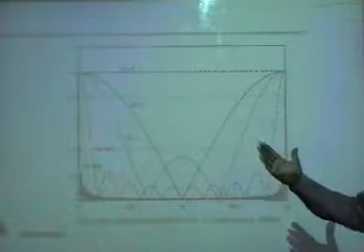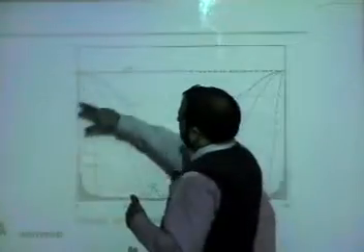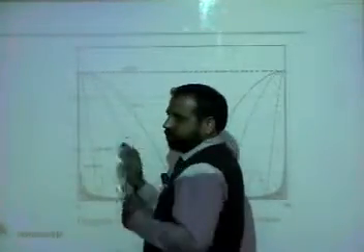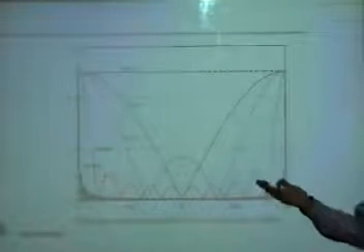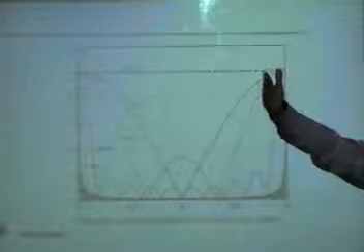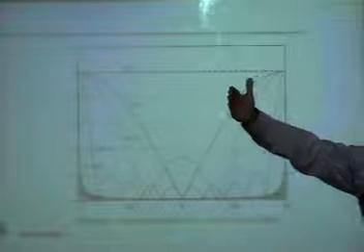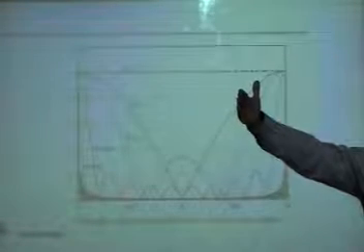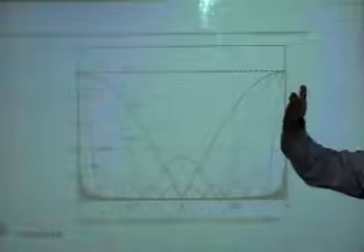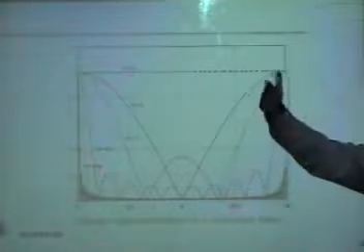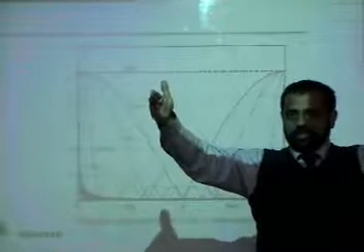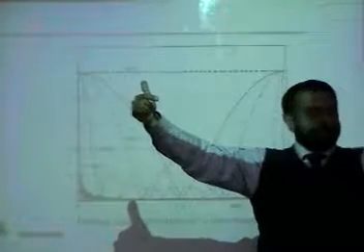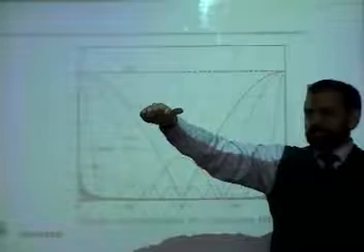This is a good example of showing how the moving average works: taking the average of more samples, you will be suppressing high frequencies. For example, what if you take a moving average of 1000 samples? You take 1000 samples, add them together, divide by 1000, then you move. Again you add 1000, and in this 1000 you are adding 999 of the previous samples. So I can visualize that I am always using 1000 samples, only deleting one sample and adding one more sample.